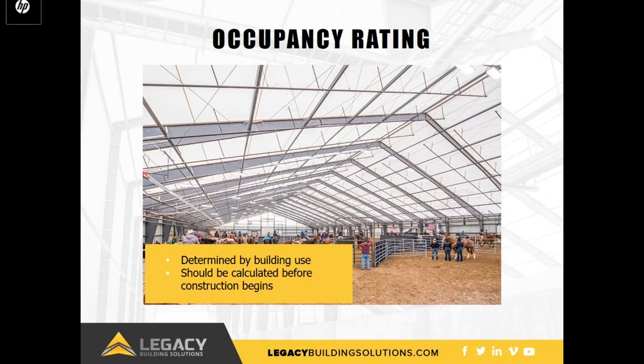Occupancy rating is determined by the building's use. A structure that is designed for regular use by people will have a higher occupancy rating than a storage building. One caveat to remember related to occupancy rating: it's much easier to get event permits in a building that is rated for higher occupancy. If you plan on holding public events, please make the investment in a higher occupancy building before construction begins. Retrofitting an existing building for a higher occupancy rating can be expensive and time-consuming.